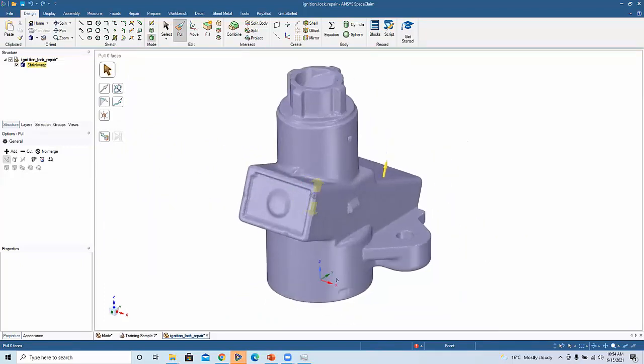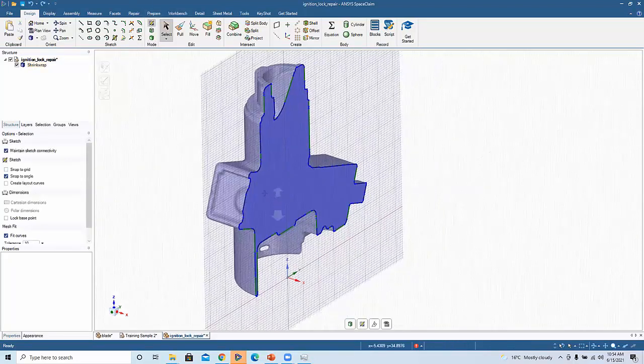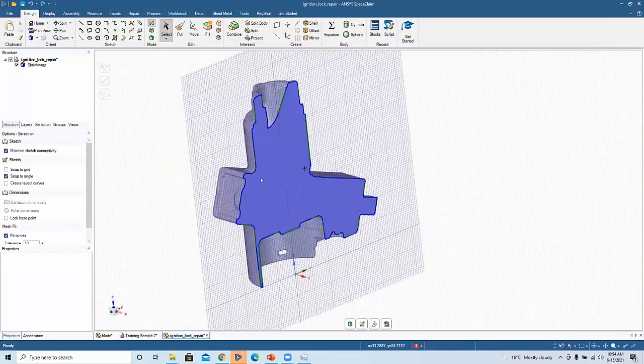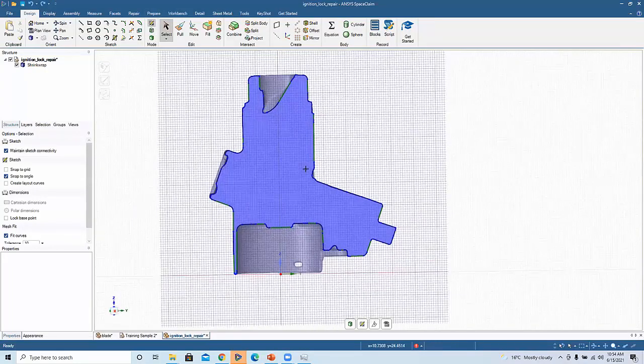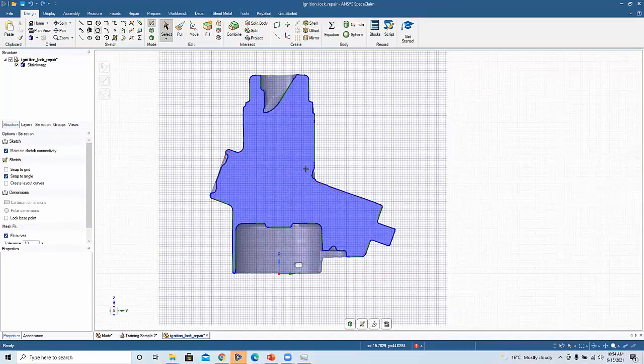Also, another thing to note is that when I'm doing reverse engineering, the UpTo command is actually quite useful. For example, let's just say I wanted to start reverse engineering this model. I can create maybe a block here on the side to retrace this block here that I want to generate from the reverse engineering of this geometry.